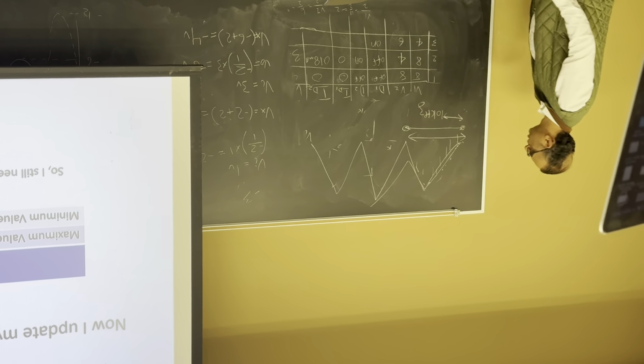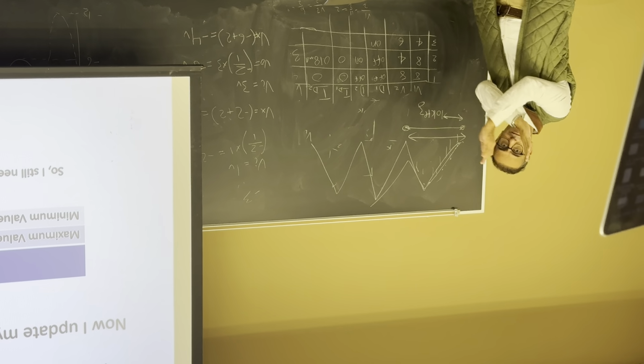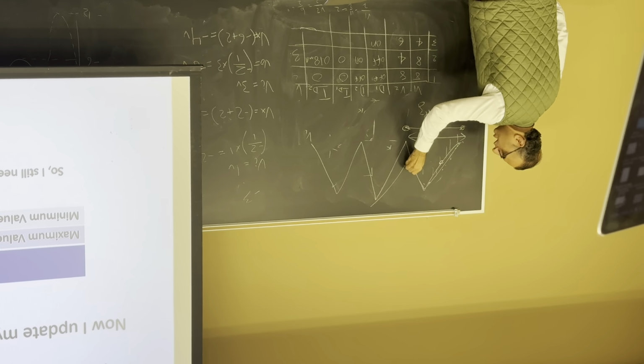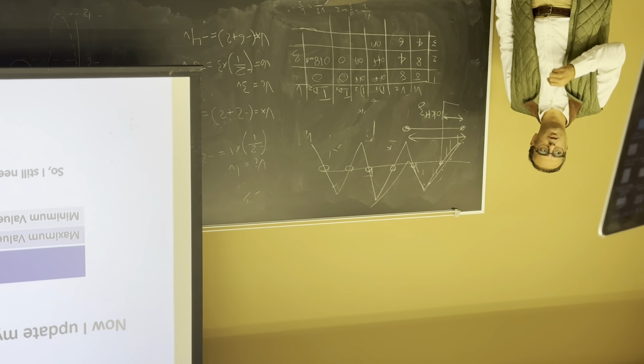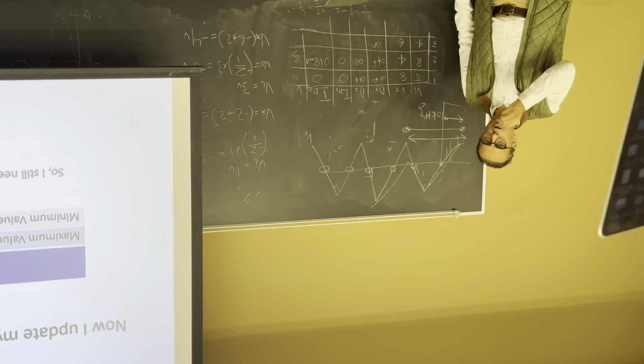If they're well synchronized with this, they shift 90 degrees or 100 degrees, and they sample only these points. Just simple. If they can synchronize the ADC sampling at this point, they are capturing RMS automatically. They don't implement an RMS calculator the way that we think. We do it, but this way.